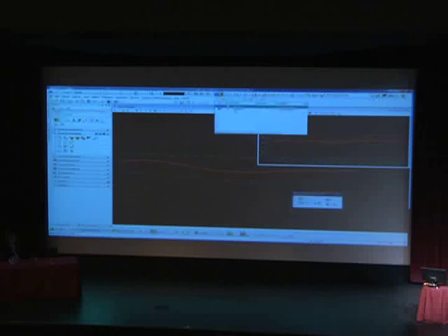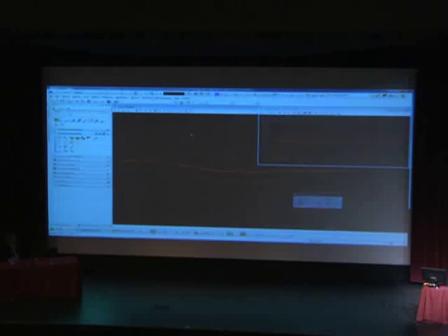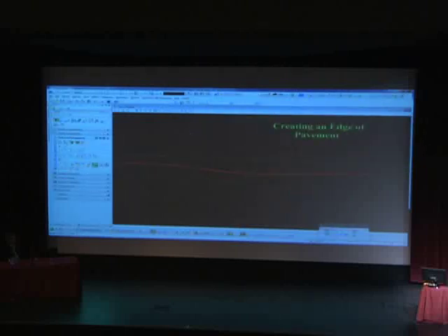Now, just showing you here that the model space created a 3D space automatically. So in a 2D seed, anything that gets a Z value will automatically create a 3D model space. Treat those two models as completely different DGNs because they're completely different model spaces.